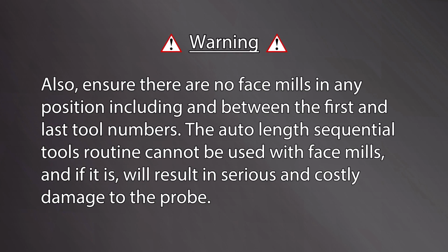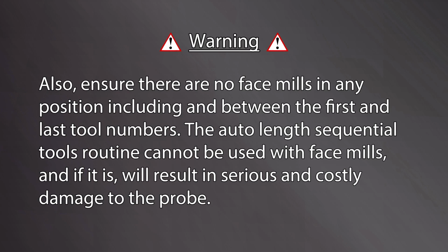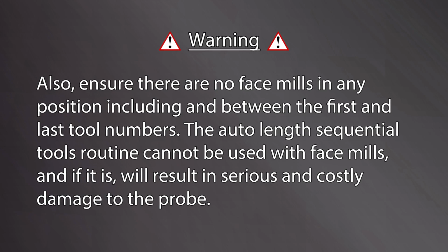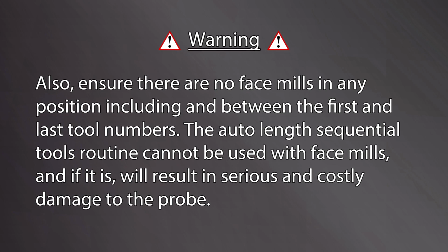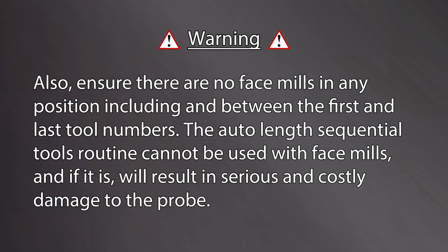Also ensure there are no face mills in any position, including between the first and last tool numbers. The auto-length sequential tools routine cannot be used with face mills, and if it is, will result in serious and costly damage to the probe.